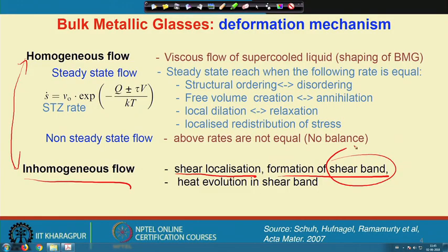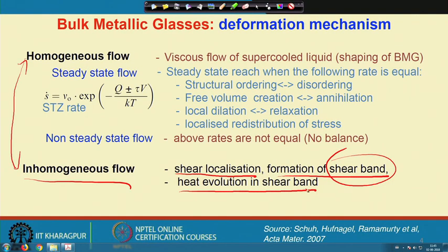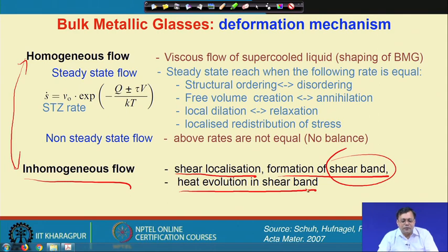In the next couple of slides, I will show you what the appearance of the shear band in a glassy solid is like. And since the stress is localized, some part of the work must be converted into temperature. Therefore, there is some heat evolution in the shear bands, and these are some of the important aspects of today's discussion.